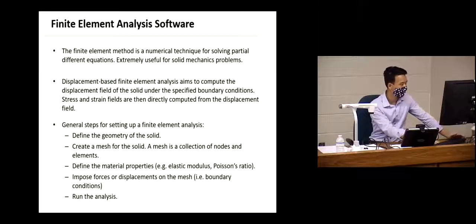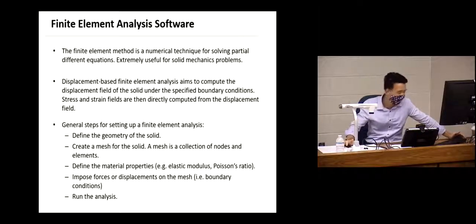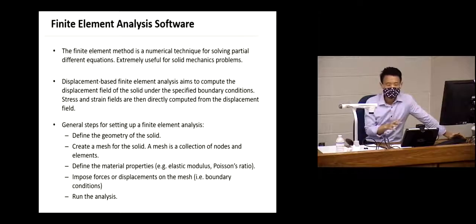Of using FEA. Now, I think there's one other thing I forgot to say about this. There's a caution about using finite element analysis. It does all the work for you, and so your responsibility as an engineer is to be able to interpret the results, right? Because finite element analysis is a tool that gives you some numbers at the end of the day, and you can't trust it. Okay?